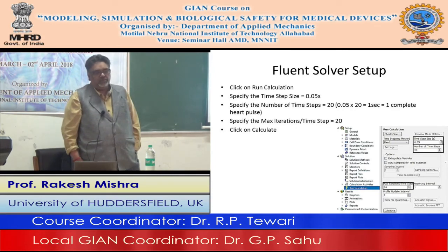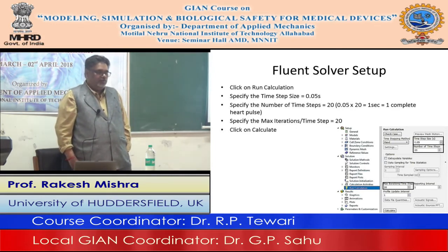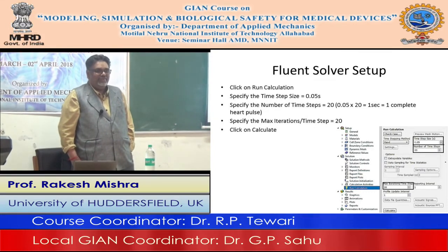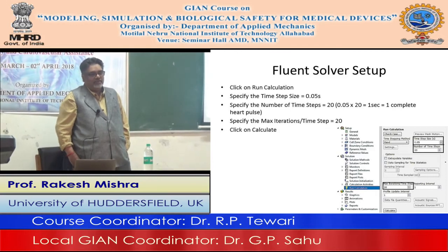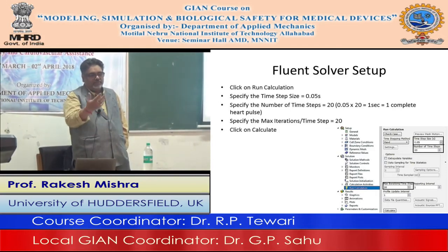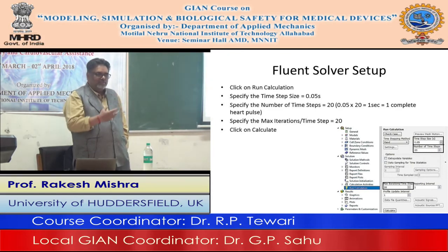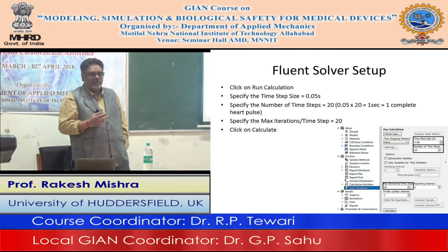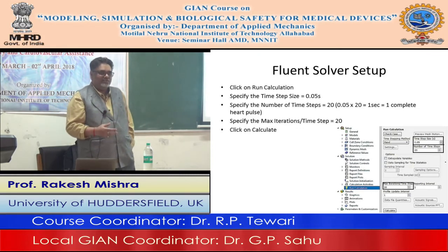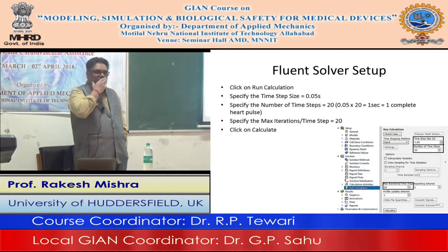a problem actually. We are using CFD to understand a phenomenon, but we don't know the phenomenon. So what we have to do is run it initially, see what type of things you are seeing, and then the best thing is to reduce the time step and see whether it is changing. Keep on reducing it till it stops changing. So then you are having at least time step independence, that now your results are becoming independent of time step. That is what we do in most cases.